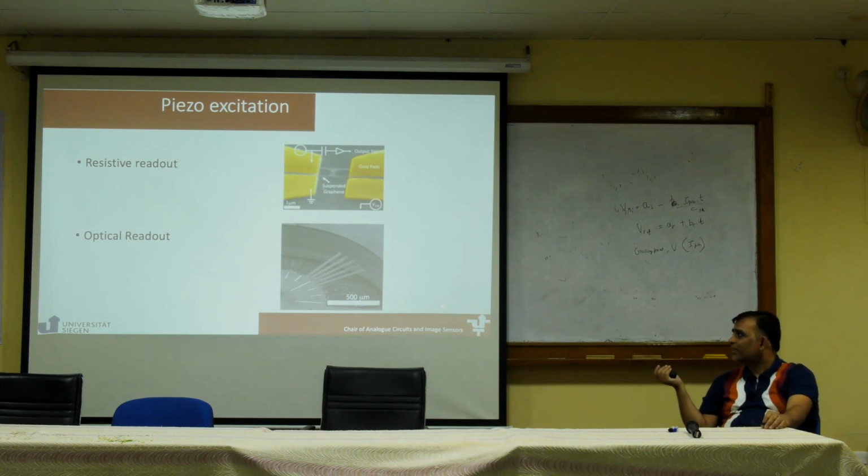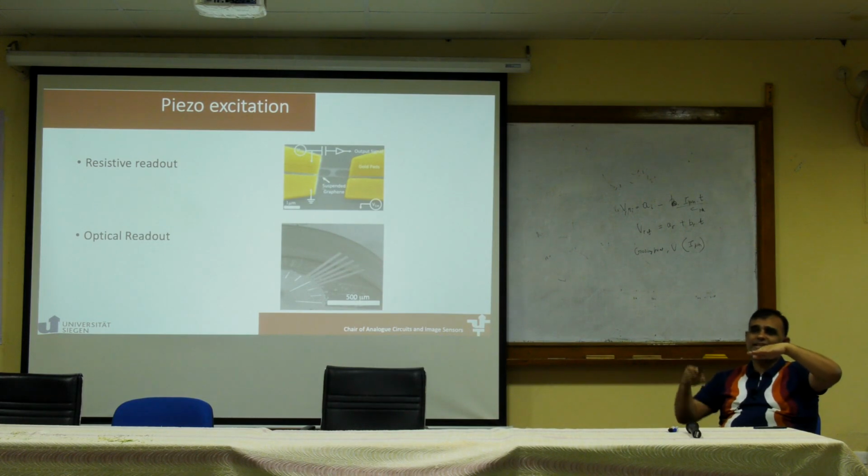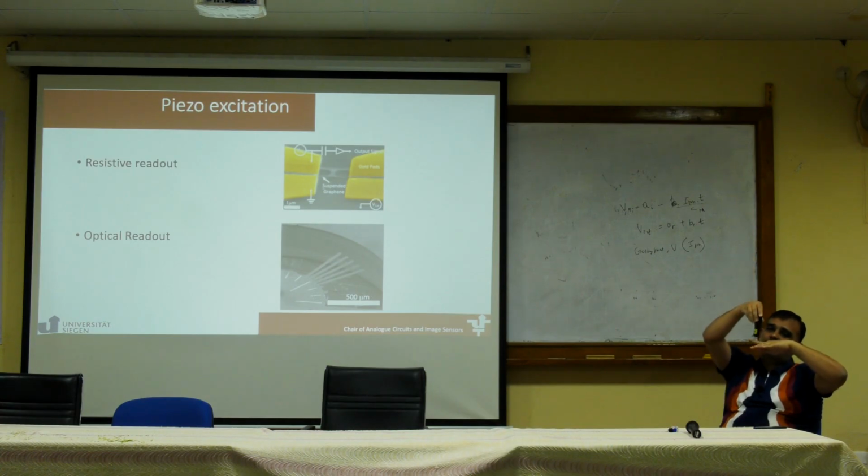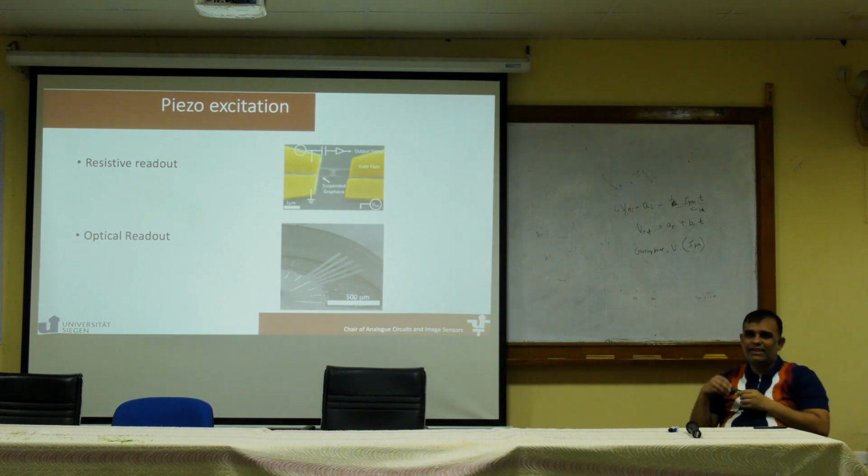Here's another example of a circuit which we made with Professor Deepak Uttamchandani at Strathclyde University. This is electrically readout. Now I have got 5 such cantilever beams. Why we made 5 we will see shortly. These are freely hanging, so they're moving up and down. In this case, we basically applied a laser beam on top of one of these and then looked at how much movement is taking place. So this is an example of piezo excited, resistively measured or optically measured.